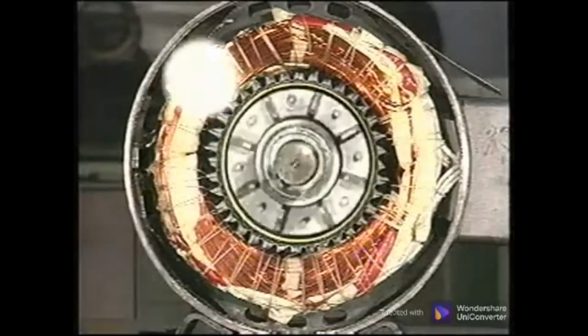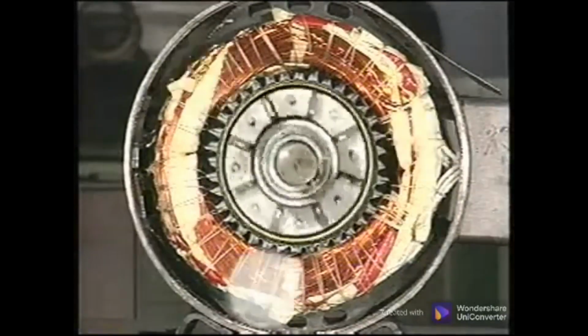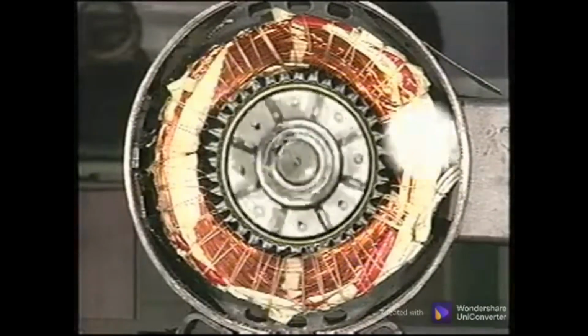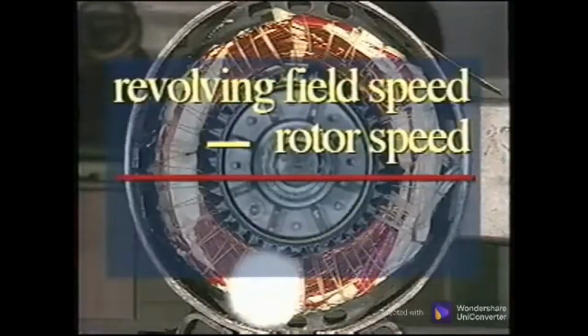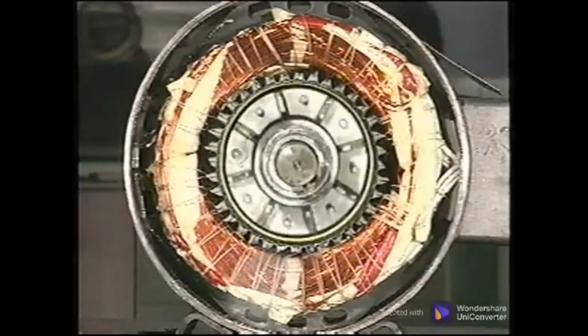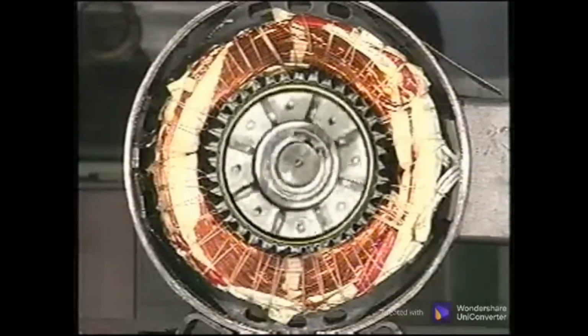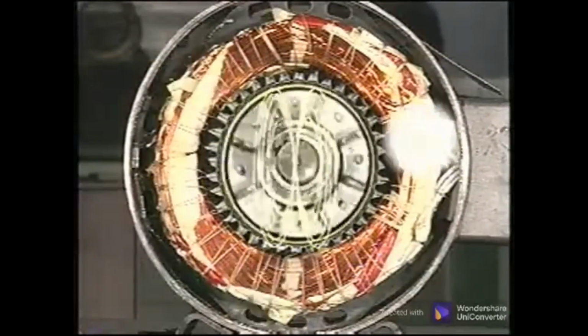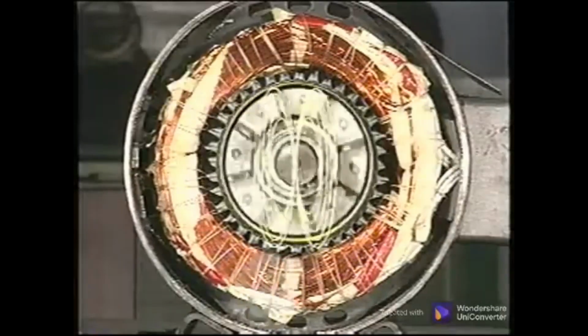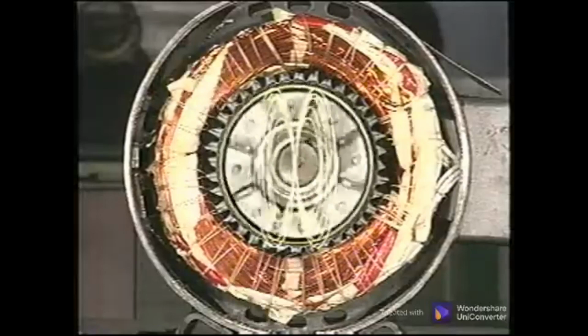The stator's and rotor's magnetic fields interact based on the principles of magnetism, causing the rotor to spin. The difference between the revolving field speed and the rotor speed is called slip. When the rotor is running near the speed of the revolving field of the stator, very little voltage is induced in the rotor, meaning that it is drawing very little power from the stator and therefore has low torque.